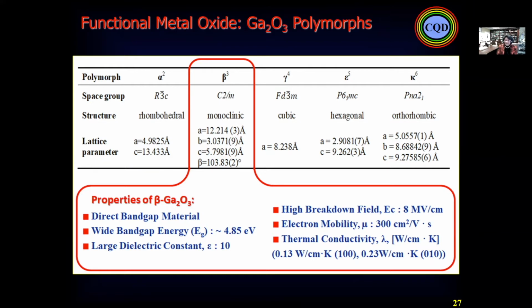So there is another possibility, gallium oxide. And gallium oxide has, again, for one part, unfortunately, it is polymorph. It means that, as you can see, the symmetry is not zinc blende, so that's a lower symmetry, but it is a direct band gap material, and at the same time a large band gap, with a high breakdown field. And at the same time, for this material we can make a substrate excellently lattice matched to gallium oxide beta phase, and we can make n-type or semi-insulating.